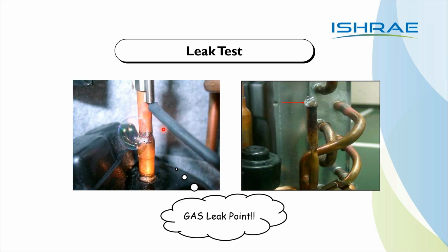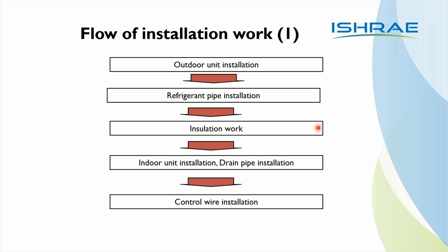Then these are some of the minute places where you can develop gas leaks. Please note, it is very, very difficult for you to check the minute leaks. So please take proper care while brazing. Do a proper pressure test. Minute leaks take longer time to detect.